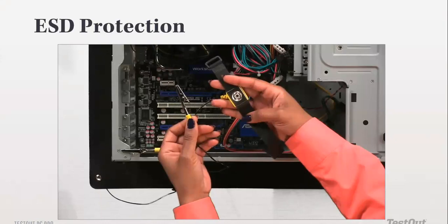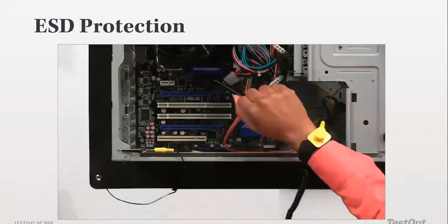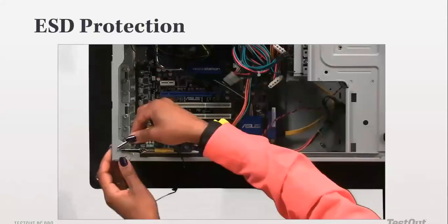So one thing you should always make sure of is that before you work on a PC, you disconnect the PC from current, and while working on sensitive components, wear a wrist strap, an electrostatic discharge wrist strap. So this is how it is being worn. It is worn here and connected to the PC case. You connect it to the PC case as you see.